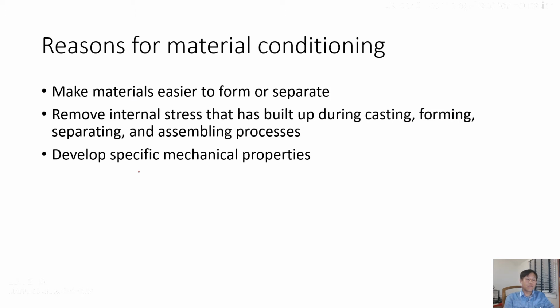There are many reasons, but we want to highlight three main reasons for material conditioning. The first one is to make material easier to form or separate. And then, to remove internal stress that has built up during the casting, forming, separating, and assembling processes.